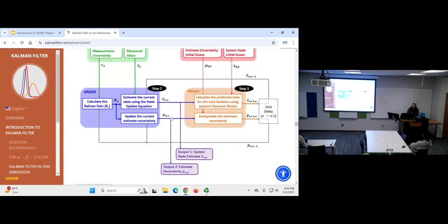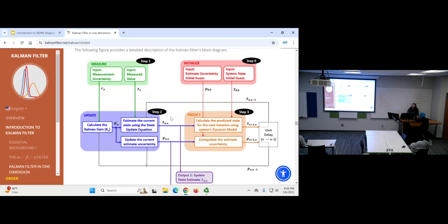If you do make one, like I said, the models get complex, so don't start out going, I'm going to fuse every sensor in my electronics toolbox. It's probably a good learning experience, but it may not work. You may want to just do the two-dimensional case. The other thing you learn with this is the assumptions you can make. It's physical modeling, right? That's all you're doing. You don't always need to model acceleration to get an accurate navigation result. You can make assumptions about some of these physical attributes and what your system is doing.